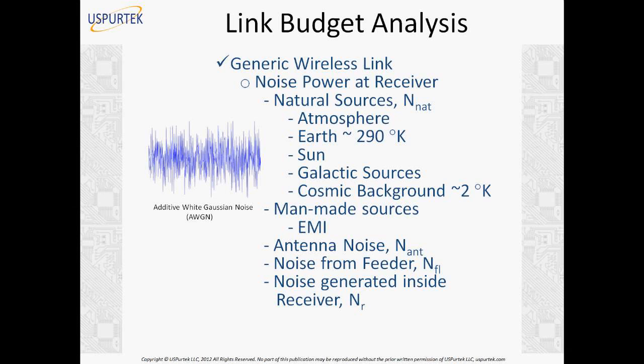Anything above 0 degrees Kelvin radiates noise. It radiates radio energy, which manifests as RF noise, and we do see it in our receivers. If you hook up an oscilloscope, it will display like additive white Gaussian noise, AWGN, and it's spread out equally over all frequency bands, right?